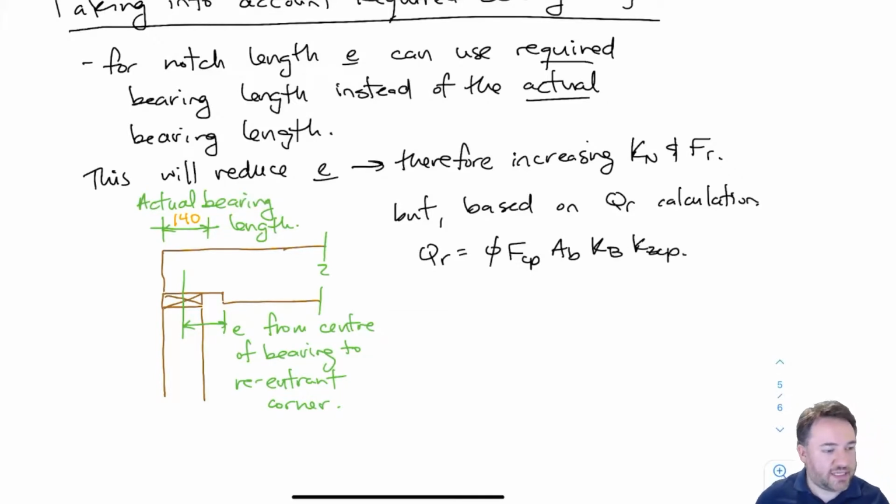So recall that this is the bearing strength for effective all applied loads. This is the bearing strength calculation. If I do this calculation to find QR, I'll probably find that QR is much higher than the QF, the maximum load at the bearing surface, that's being applied at that location. So usually my QR might be way greater than I need. So then what I can do instead is reverse this equation and say this is what the load actually is, QF, and what would be the area of bearing surface that I would actually require in order to resist the beam.